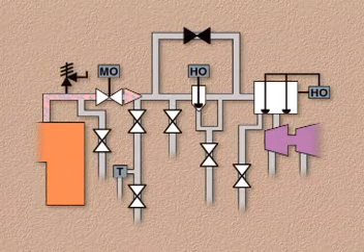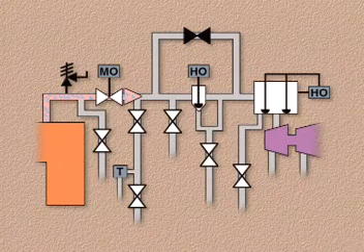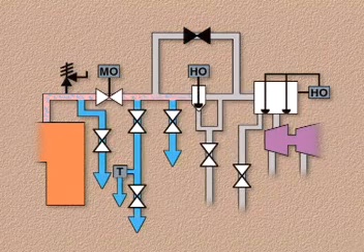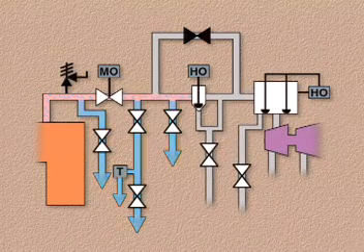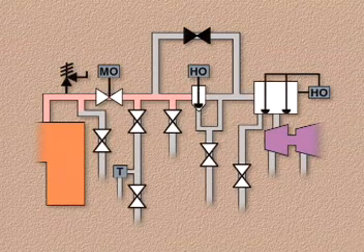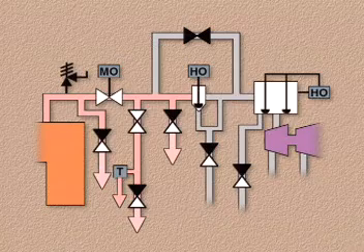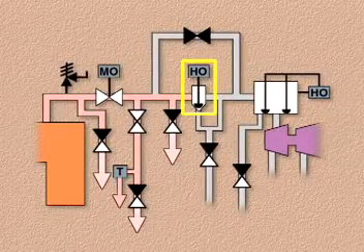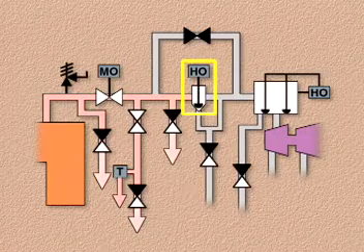Some of the steam flowing into the relatively cold system condenses almost immediately, and its heat is transferred to the piping and components. The condensate that initially forms in the cold piping flows out the drains. When the system has been sufficiently heated, steam begins blowing out of the drains. Then the drains may be partially closed. The main steam stop valves remain closed to prevent steam from entering the turbine.